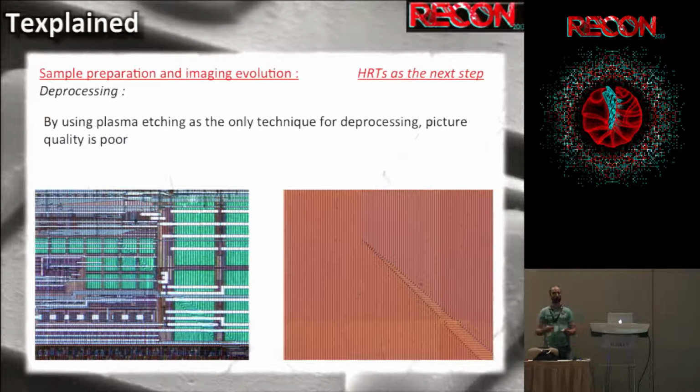So it's cool. I remove the oxide, I see my metal, I take pictures, I remove the metal, and I do it again and again and again. But if you do this, you will not succeed, because each time you remove metal, you have the shape of the metal line that is staying on your chip. And now you do the oxide etch again, and you just increase the shapes everywhere on the chip.